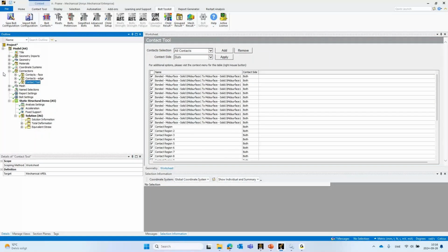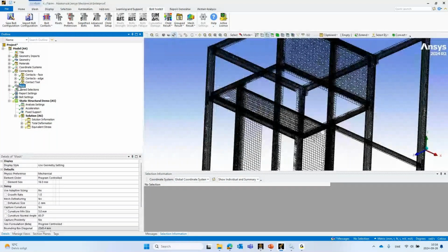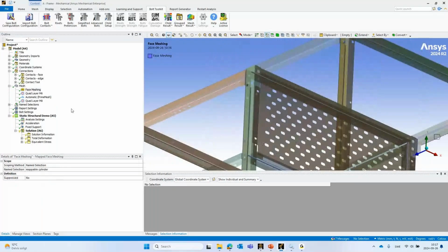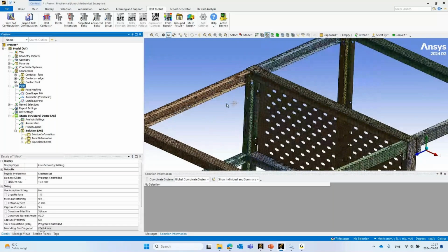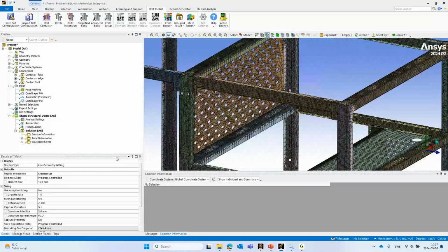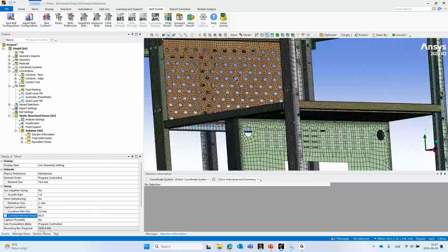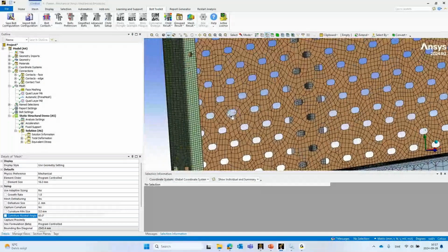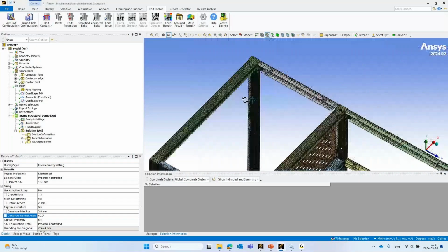Next up is meshing. So how to mesh this sheet model. What I did here was assign some global curvature to deal with all these bolt holes, how to resolve them, but not too much. So quite coarse here, 60°, making it in general good.